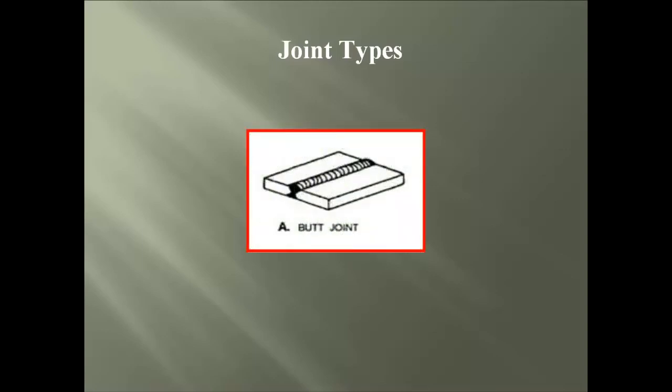Okay, before we dive into the different symbols for each type of weld and finishes, we need to understand there are situations that require these symbols, and that will start with the 5 basic joint types that are created with connections of structural steel material. The first joint is the butt. You will have 2 different plates that will be fused together by the actual weld.